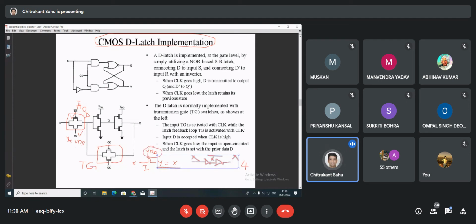In a pass transistor, it will pass the information only when the NMOS is on. So here also it is connected in parallel. Any information coming at this node, X will be equal to X here if the clock is working. So this removes the need for CMOS, where we required two inverters. Here we can utilize only two transistors instead of 4.